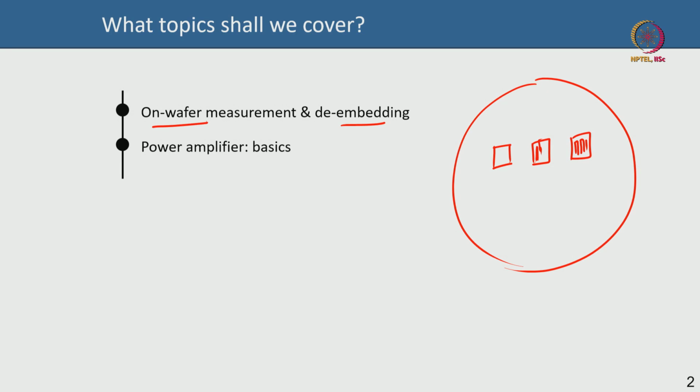Now this is not the only way to measure; there are many other ways, and in the real world you will need different approaches. In an on-wafer measurement, if you have an active device like that, you have a CPW pad, which is a coplanar waveguide pad, to measure the on-wafer devices. You have seen this picture many times in the course: ground, signal, ground. So you have source on both sides and in between maybe you have the gate. The gate is the signal. These kinds of structures are there to enable on-wafer measurement of, say, S parameters or power, things like that.